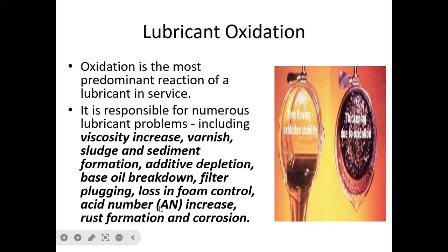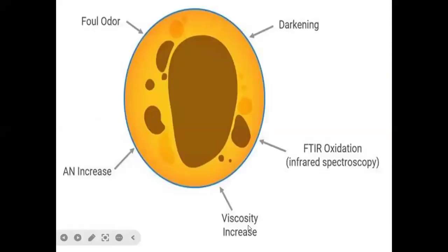A higher acid number also means a lower base number, rust formation, and corrosion. As you can see here, in the before and after, our viscosity here is actually lower. And upon changing your oil, the viscosity now thickens, or is increasing, as evidenced here.